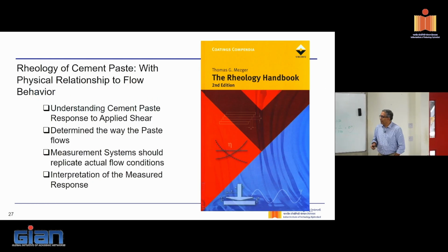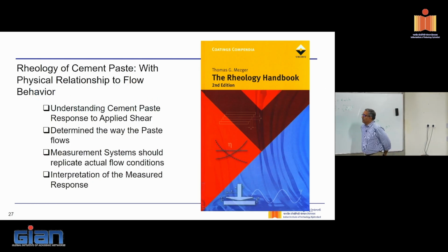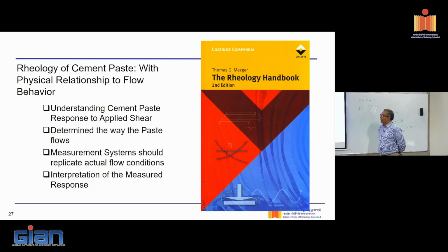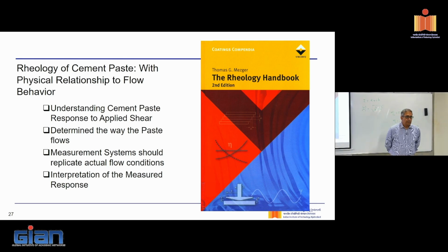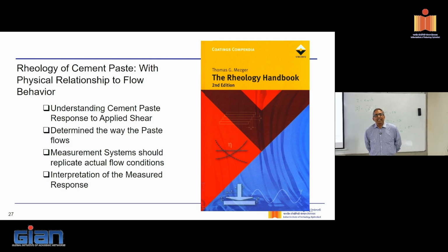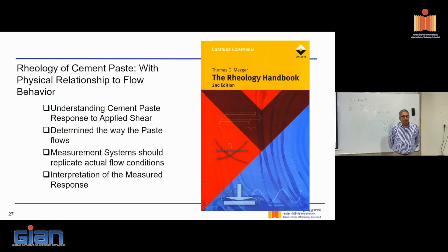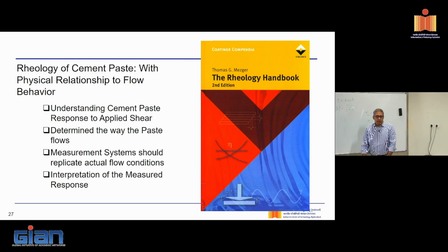The one thing I'd like to point out is what are we doing in rheology of cement paste? We want to understand the cement paste response to applied shear. The issue is we cannot directly measure shear. So what do we do? We measure torque, we try to infer the flow, and from there we come up with this rheological response.